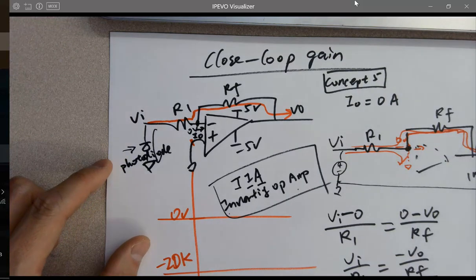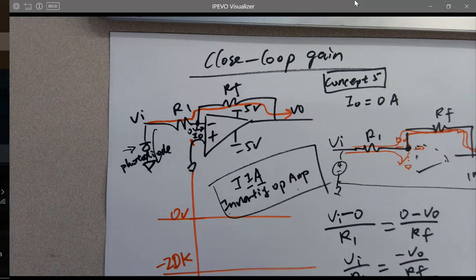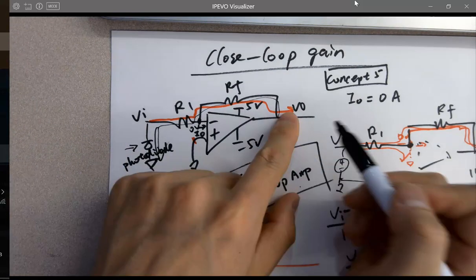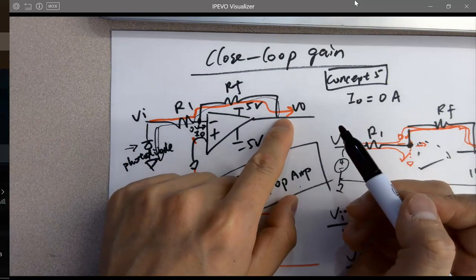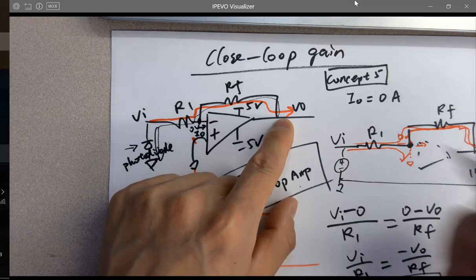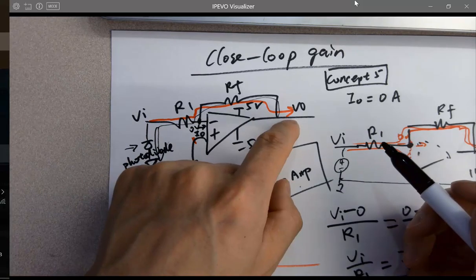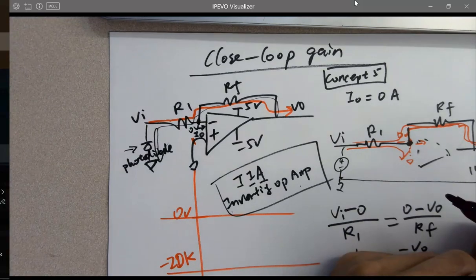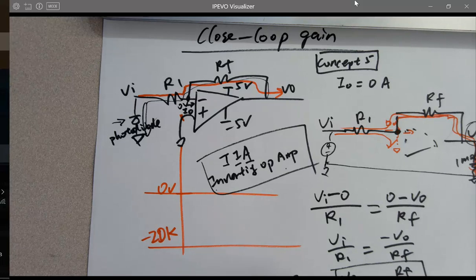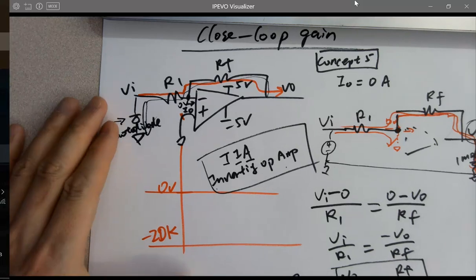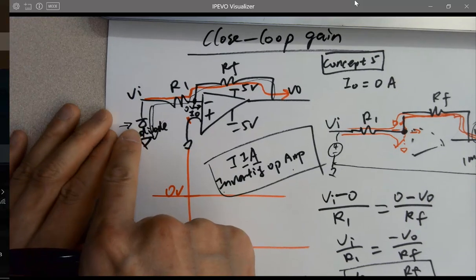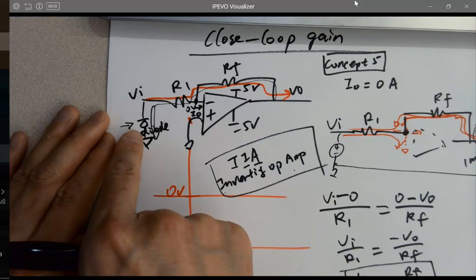You have a photodiode. You shine light onto it, then it generates photocurrent, which will flow through here to ground and create a voltage drop, which is V out. Depending on the intensity of the light, you get a different voltage. That's why the pixels have different intensities. The current comes out of the op-amp? No, the current comes from the physics, the electrons in the photodiode.